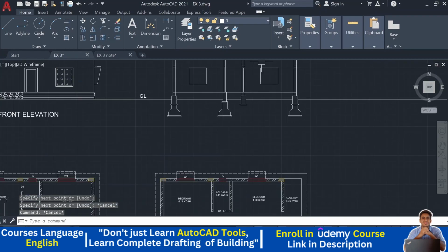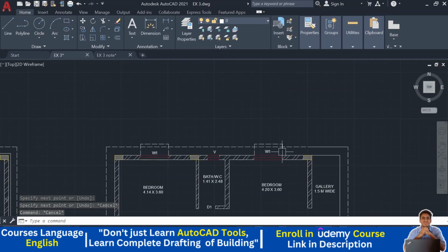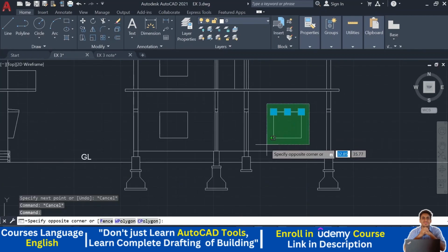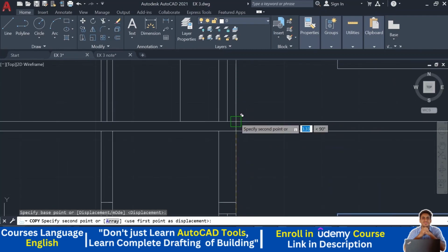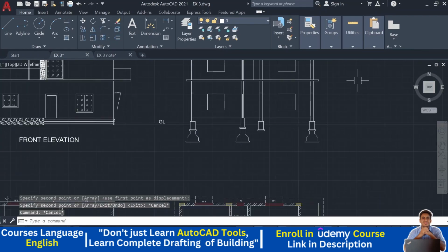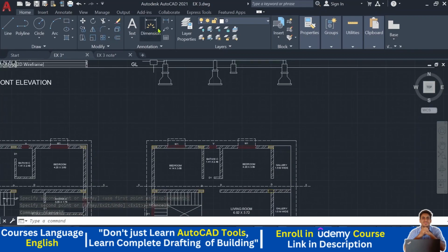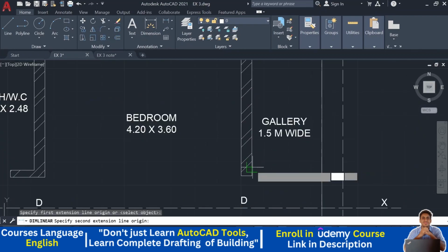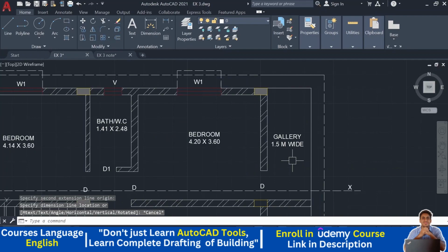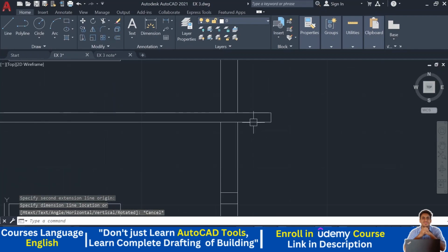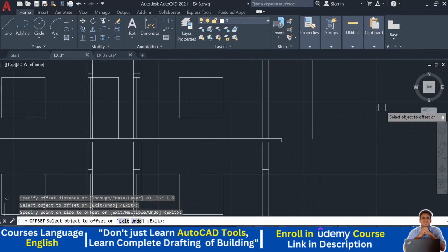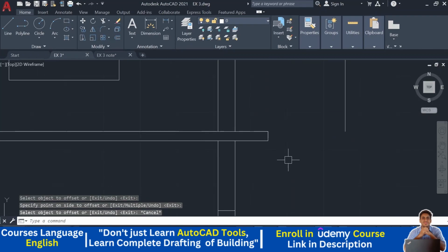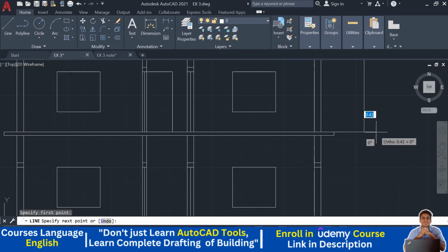Again, okay. So I come here, again this window is the same as below. So I copy this and paste it over here, okay. So next, this door and this balcony. So how far is this balcony extended? 1.5 meter, and after that this slab is projected, okay. So this slab I project here, offset 1.5 meter, okay. And I extend this, EX. So from here it is slab projection.